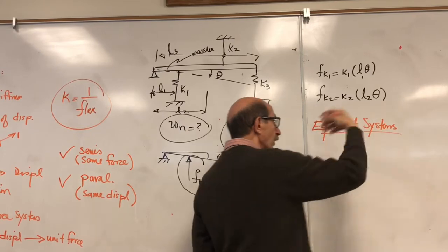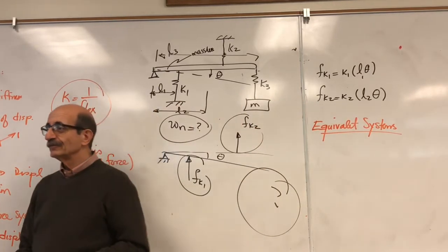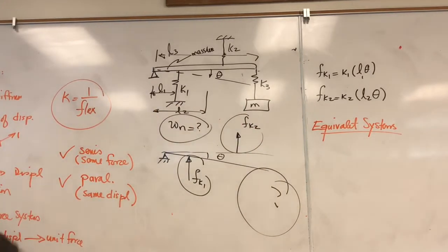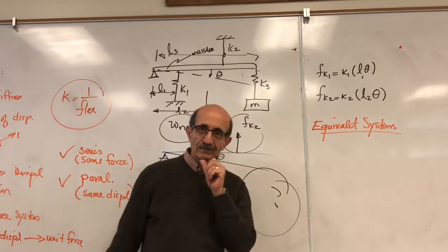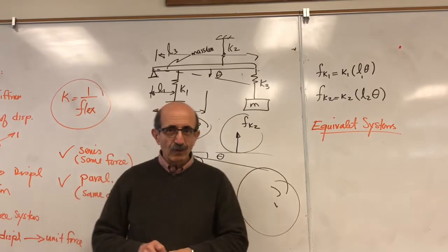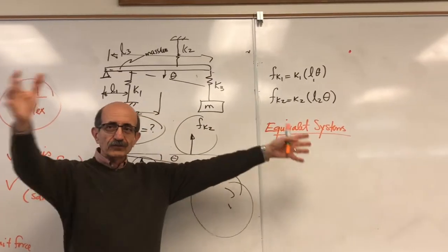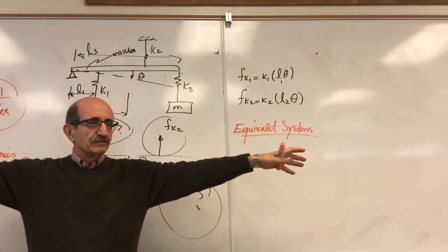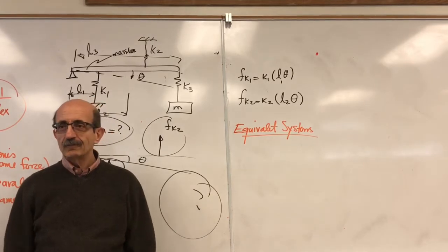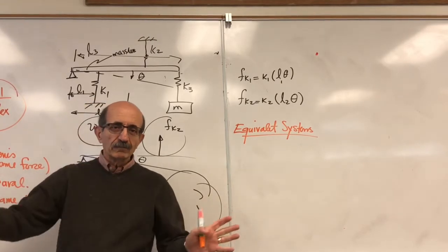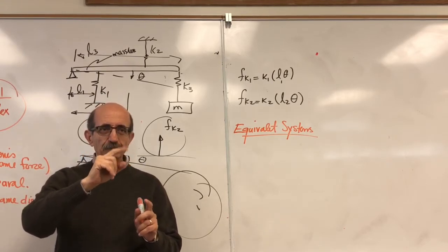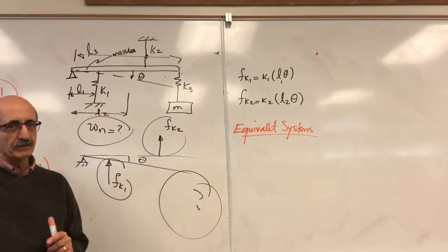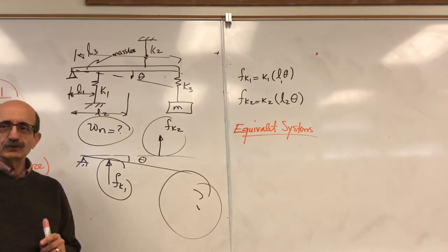That was built upon the concept of couples, moments and resultant forces. What was the concept of equivalent systems? Very simple. If you had several forces spread out through a rigid body, you could get rid of all of them and find one single force that you can put at any location you want. How do you do that?